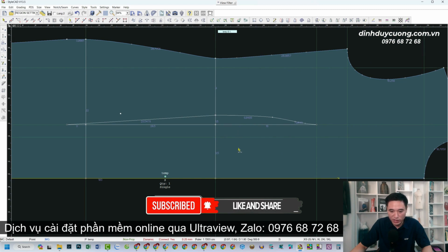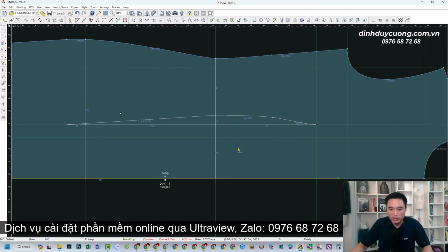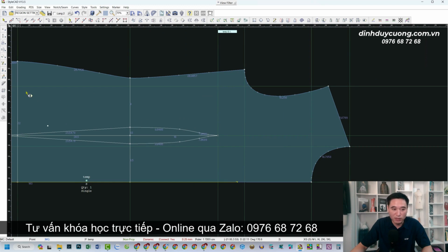First, you'll need to hold down the left mouse button and then press the F key. Next, hold the Shift key and carefully select this specific upper edge. After you have done that, press D and continue holding the left mouse button. Now, select both the start and end points of this pleat center line. Instantly we can see that the opposite edge has been generated.